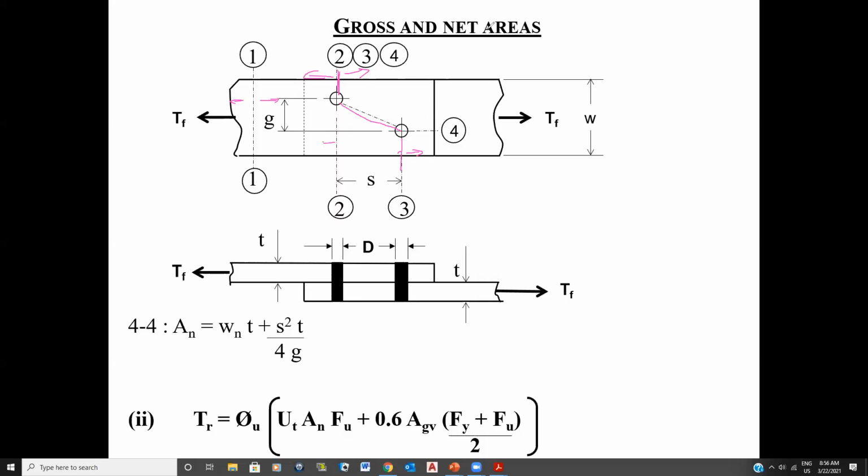So what you're gonna have to remember, just for this little section here, it's no longer the tensile resistance that's resisting the steel, it's in shear. Everybody sees that? Just for this little section here, it's in shear, and that's what all this is about. This is to calculate the value of that little bit in your possible failure plane.